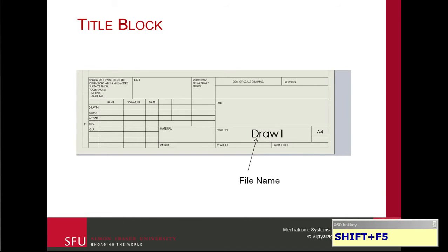So we mentioned the bottom part where the name actually updated. This is known as the title block. It is useful for conveying information when things are printed. If you notice, there is additional information here. This is the finish used for machining purposes. Here it says all dimensions are in millimeters unless otherwise specified. And then here you have something called drawn by, signature, and so forth.